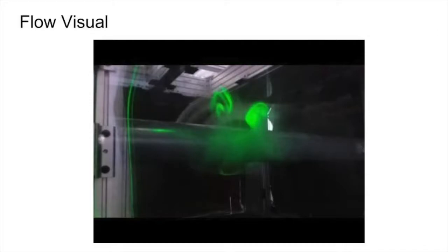The boundary layer remains laminar from the stagnation point at the front of the cylinder to the point where it separates at the maximum thickness. The resulting flow pattern is associated with a high drag on the cylinder, and as the flow swings 90 degrees from the stagnation point, the boundary layer separates because it anticipates the deceleration of the flow that would otherwise occur on the rearward face of the cylinder.